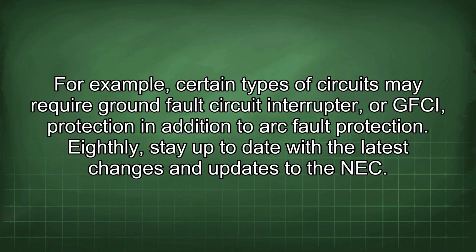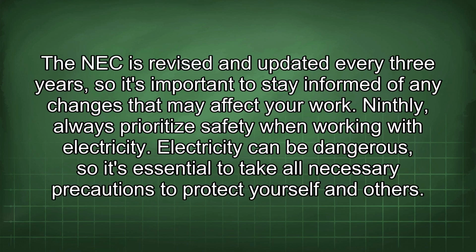Seventhly, be aware of other NEC requirements that may apply to specific types of circuits or locations. For example, certain types of circuits may require ground fault circuit interrupter, or GFCI, protection in addition to arc fault protection. Eighthly, stay up to date with the latest changes and updates to the NEC. The NEC is revised and updated every 3 years, so it's important to stay informed of any changes that may affect your work.